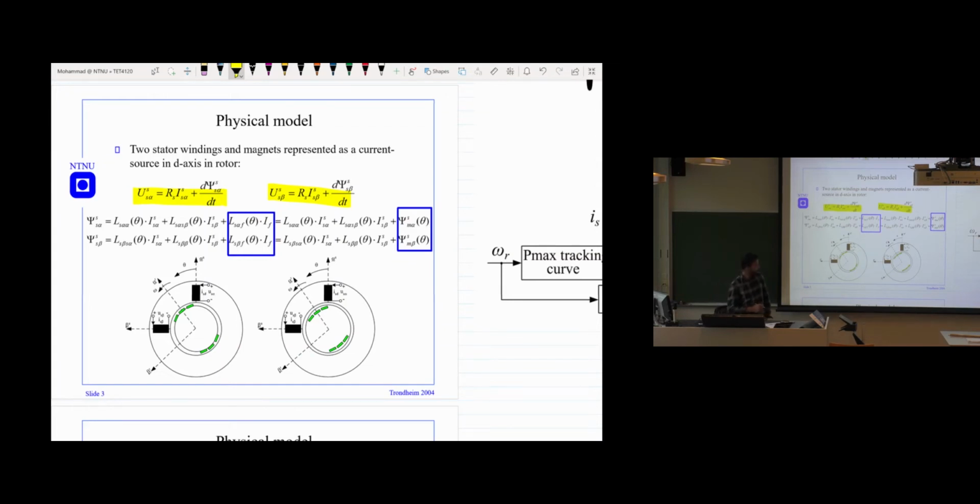And also Roy was discussing a lot how to set up this inductance equation, because this inductance equation tells us the amount of torque it can keep. So I don't want to talk that much about it. The only thing he was saying is that these two fluxes are 90 degrees shifted. This is the mutual flux that's induced by the magnet, and they are shifted by 90 degrees for the d-axis and the q-axis here.